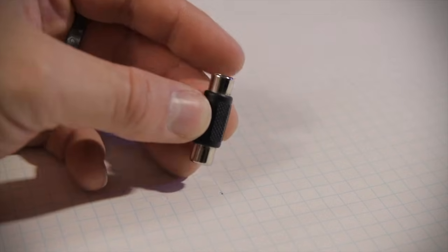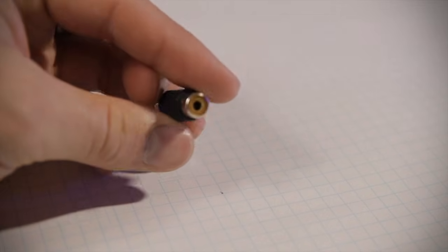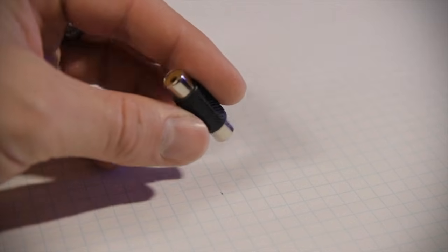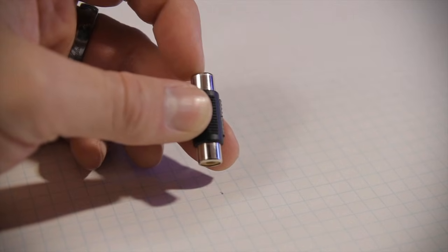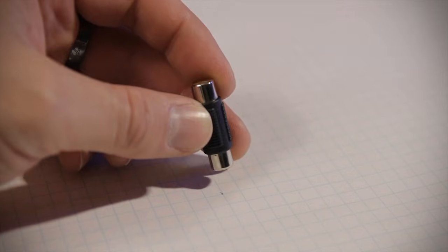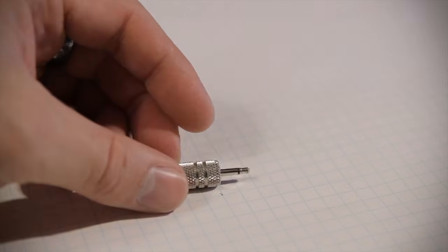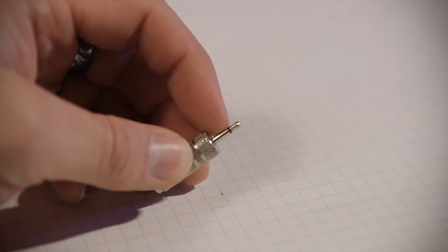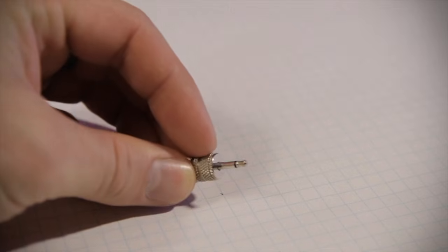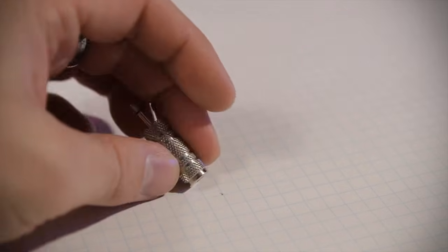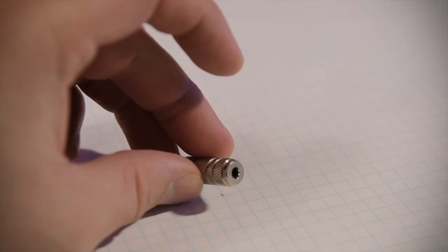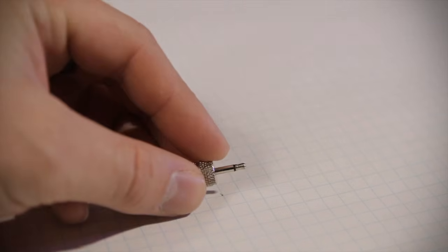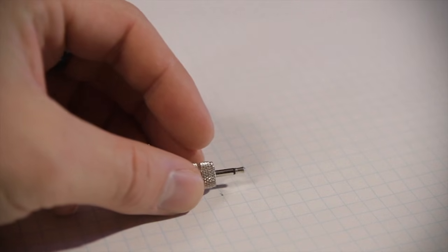Here's another cool adapter that I have laying around. This is a female RCA to female RCA adapter. So this would be useful if you perhaps needed to extend an RCA cable a little bit longer and all you had were 2 male RCA cables. So that would be the adapter you'd use. Here's another example of kind of an obscure adapter. This is a 3/32 mono plug or tip sleeve going to a stereo 1/8-inch or tip ring sleeve plug. I used this on an old Korg metronome that I needed to go to headphones.